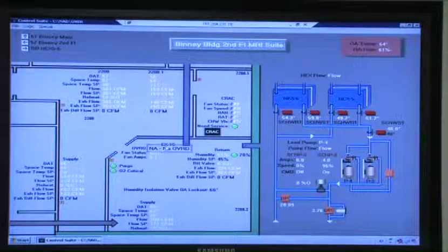So in here, we have exhaust fan 16 override. Fan status is off, fan amps is 1. I'm assuming this is strictly for the purge. That's correct. Exhaust fan 16 is for the purge system. There's an O2 meter on the wall measuring oxygen depletion. If oxygen falls below, I think it's 19 or 18.7. 19.5. It's 19.5? Oh, I was right the first time. If it falls below that, this meter will go into alarm. Will this turn red? Mm-hmm. This will show an indication that it's gone into alarm, and that alarm will come to the graphic.